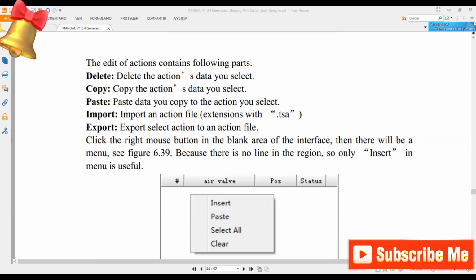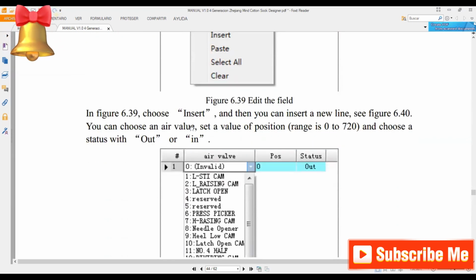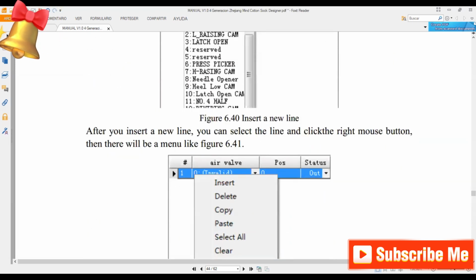Click the right mouse button in the blank area of the interface, then there will be a menu, see Figure 6.39. Because there is no line in the region, only Insert in the menu is useful. Figure 6.39 Edit the field. Choose Insert, and then you can insert a new line, see Figure 6.40. You can choose an error value, set a position value, range is 0 to 720, and choose a status, without or in. Figure 6.40 Insert a new line.